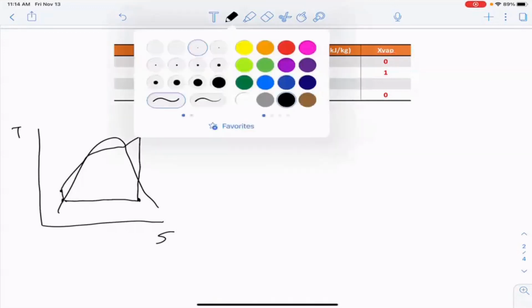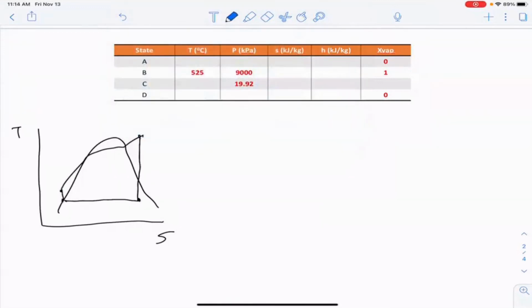Well, if we start to lift the assumptions about the processes here and here being isentropic, what's going to happen? Actually, this point A is going to come in a little bit, because the entropy should increase if it's not adiabatic and reversible. And also, this should start to move this way.